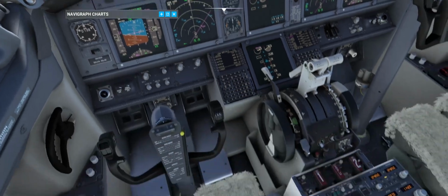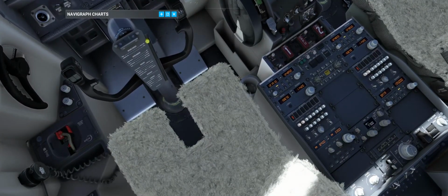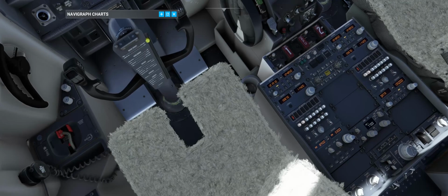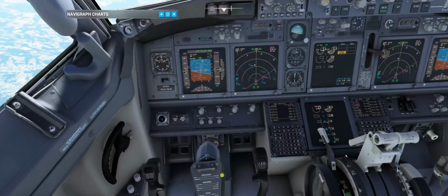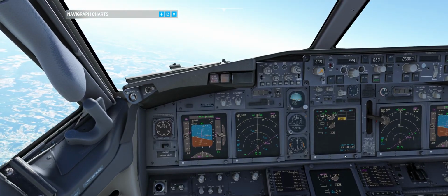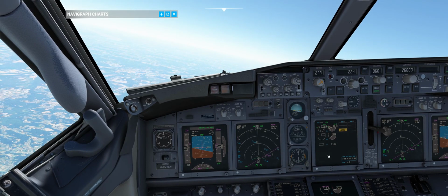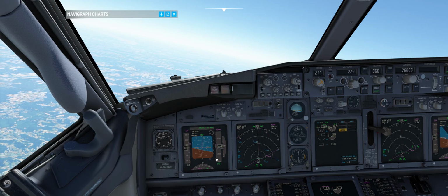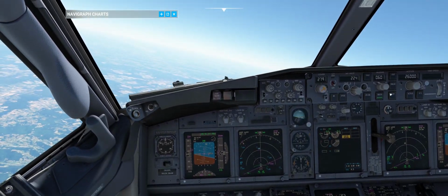And as I said before, we can adjust our force to your rudder pedals, which I don't have. Okay, so for example like this one, and we can put more thrust, and we will see if we are able to keep the speed, target speed, which was given by the cruise page for us.